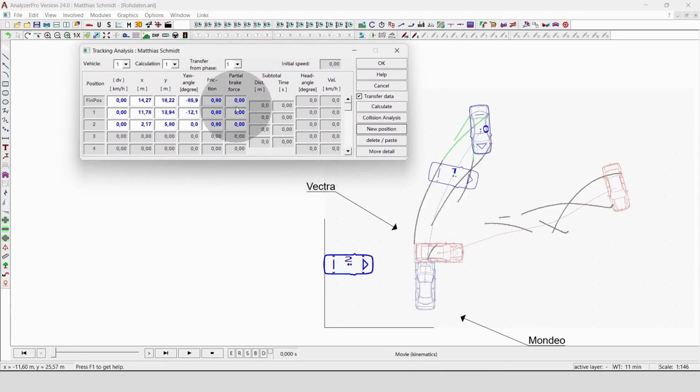Furthermore, we have two ways of letting a vehicle decelerate in that setup. One is through braking, and the other one is through sidewise gliding. So if the wheel just slides sidewise and not in rolling direction, of course it will decelerate the vehicle. For the friction between vehicle and ground, or wheels and ground, we have a friction value here. Please note that this is an average friction value for all four wheels.